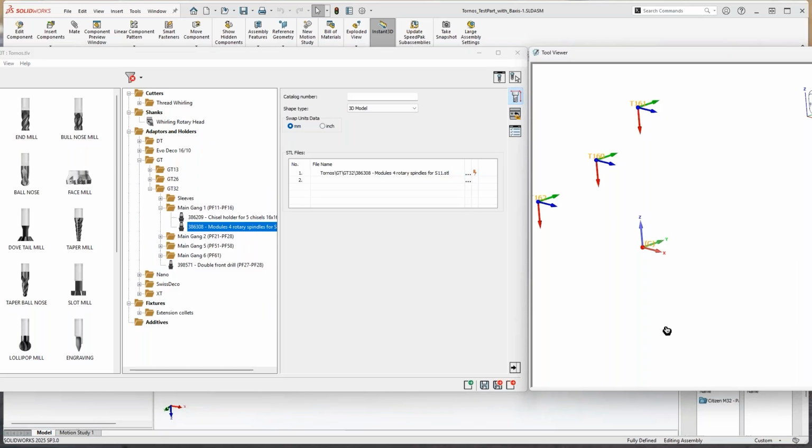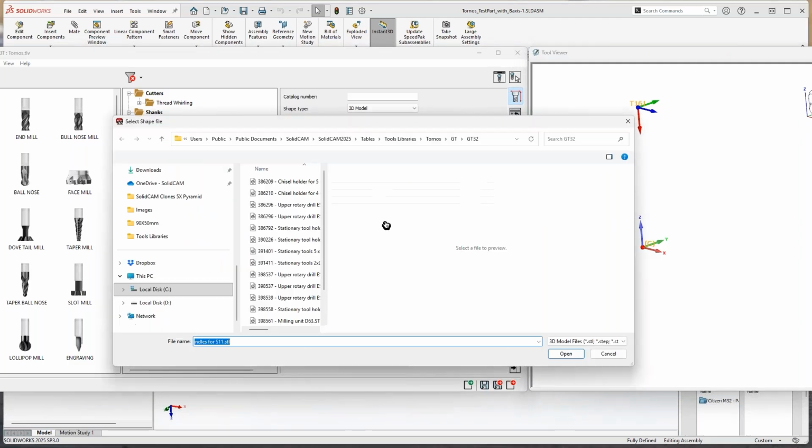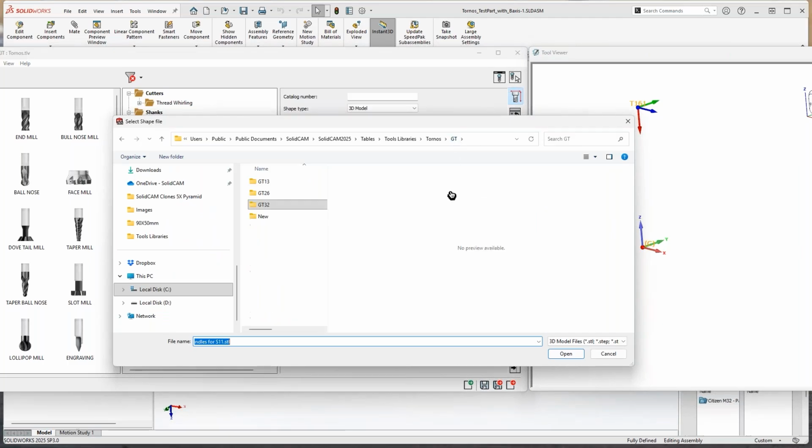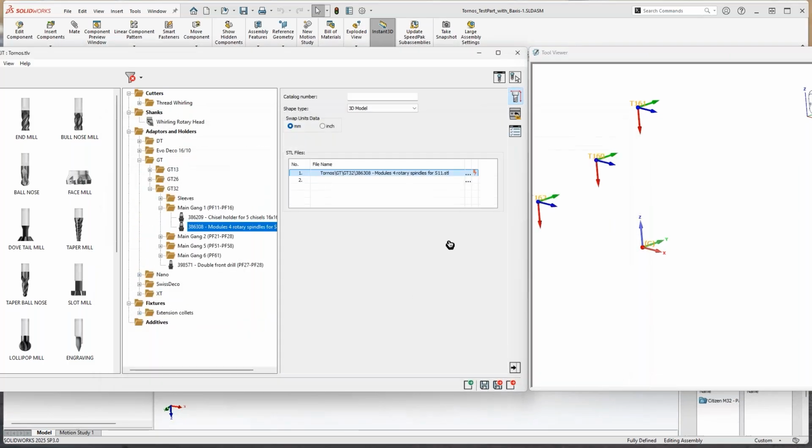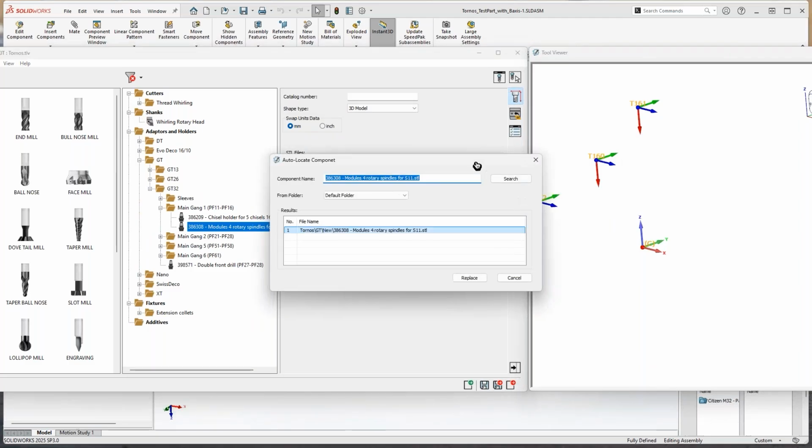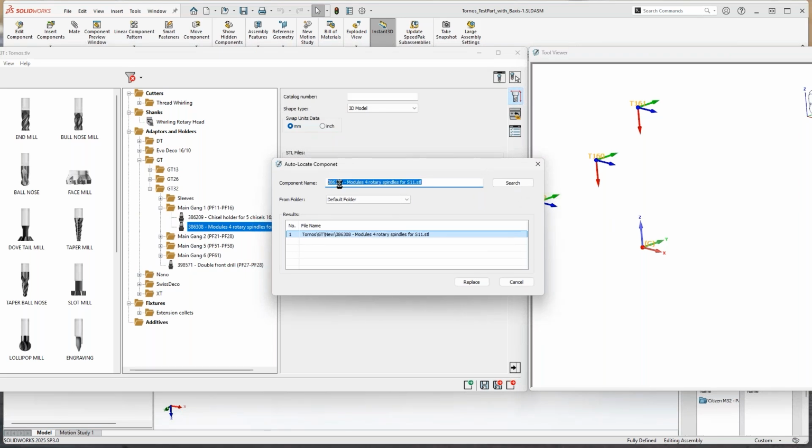So how can we restore the link? Usually the way of doing this was just by clicking on this. In this case, it's easy because I know where this file is. And doing it individually for each component, it's crazy. So I can go here, new, and just relink it, and it will be just fine. Yes. But now you have an option of doing a right click, and you have here an option, auto locate. Once you click on this, it will automatically insert the name of this file into this field and give you all the options. We've searched all your library where this file actually is located and provide you a new option.